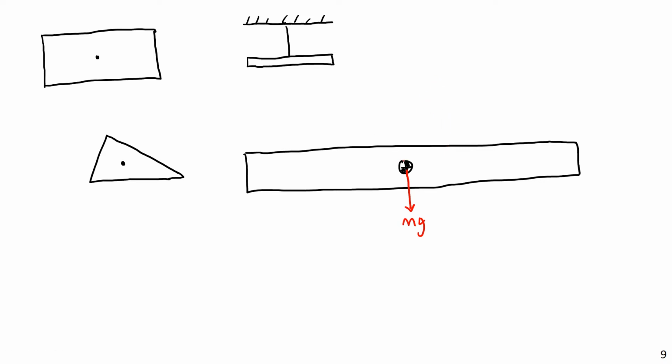And if I'm trying to make this thing hang nice and horizontally, that's not going to work. If I want to hang a thin horizontal object or a thin plate horizontally via a single cord, the only way I can do that while keeping it in equilibrium is to hang it right above the center of mass, or right above the centroid, equivalent terms in this context. So again, that's the basic idea of a two-force body. If you want to have only two forces on a body, you need to make sure that the center of mass lines up with the supporting force. And that's the basic idea.